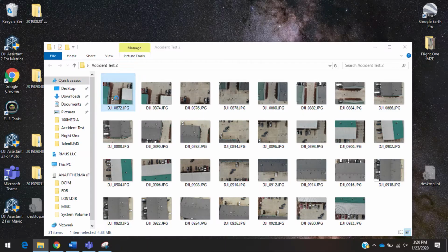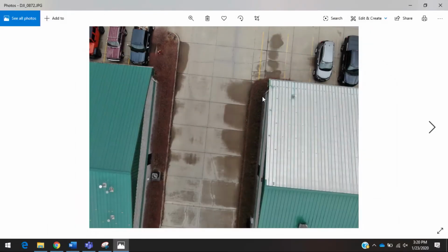Sure. So these are the photos from outside. These have been taken with the DJI Pilot app. They're a grid mission, 70% front overlap, 70% side overlap, at about 25 meters, which is about 75 feet. And that is kind of low, and we fly low and slow. There's a reason we did that, and we'll get into that in a moment.